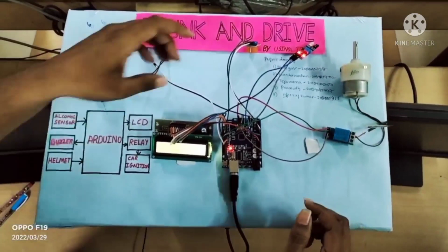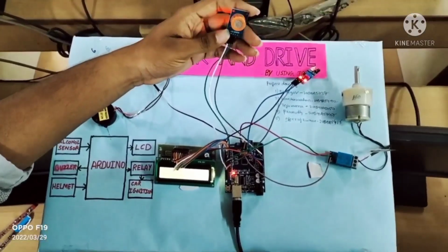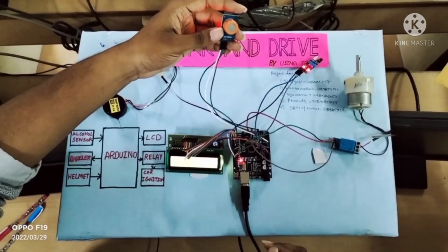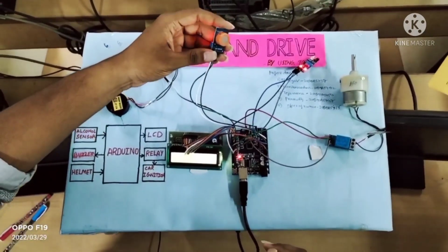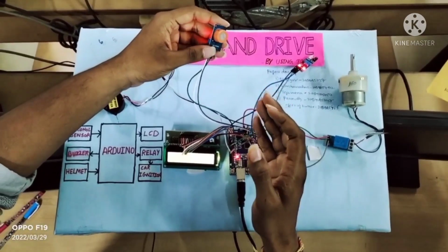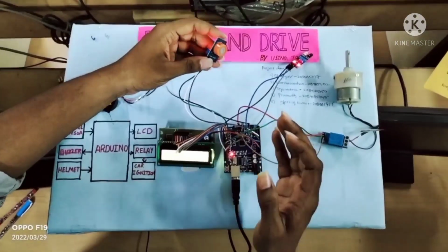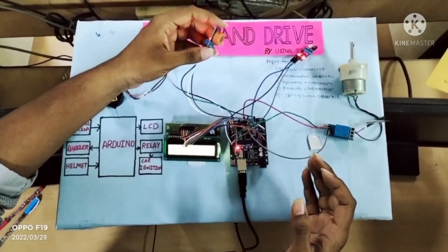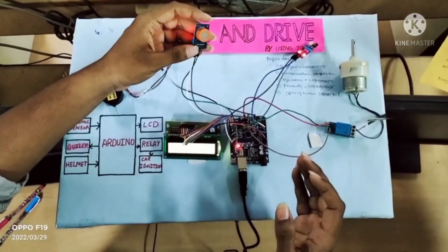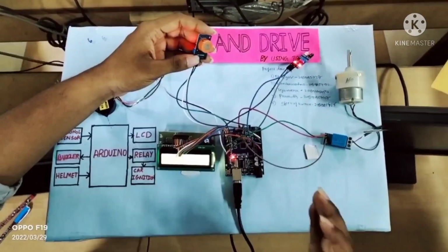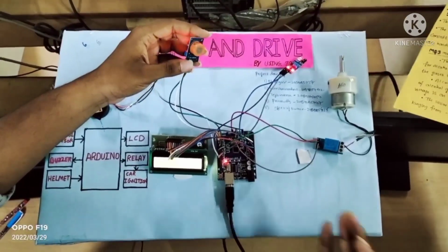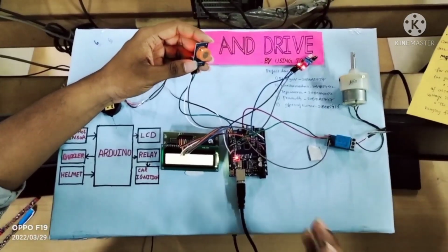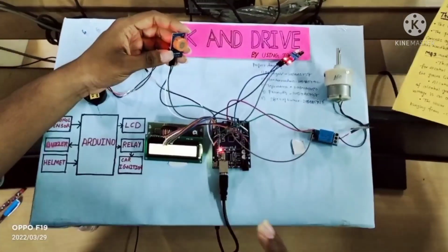And here we can see the MQ3 module. This sensor is based on MOS and used for alcohol sensing, and has low sensitivity for gases like carbon monoxide and benzene. When it detects the presence of alcohol gas in the air, it gives an analog voltage as output reading. The sensor can operate at temperatures ranging from -10 degrees to 50 degrees.